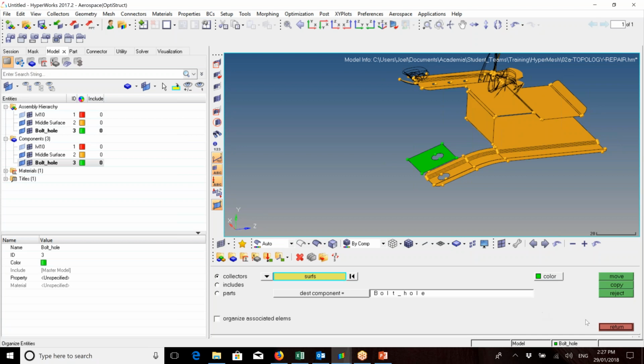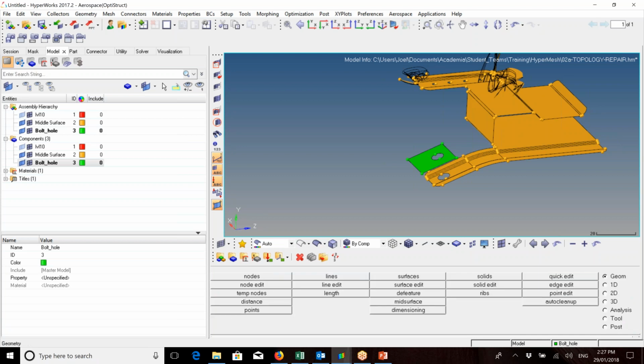Okay, so the 2D meshing in this is really fast, and it's very user friendly. A couple of things that you can use 2D meshing for are shells and mid-surfaces, but you can also use it to create what's called a skin mesh, and this helps to create a better built 3D mesh without having to do the entire volume meshing, and then you've got, say, a million elements in there that you need to check one by one.